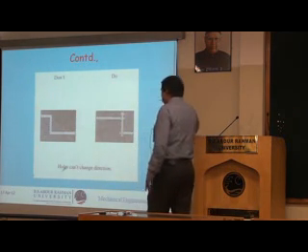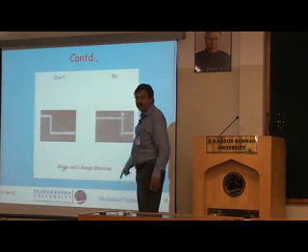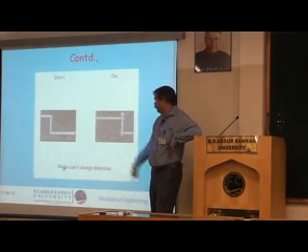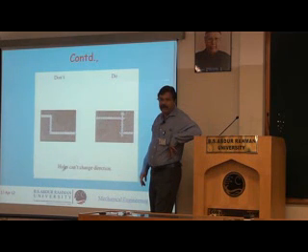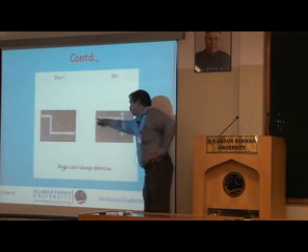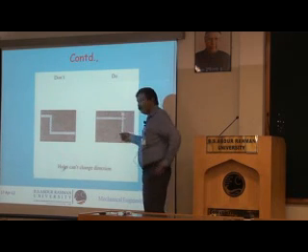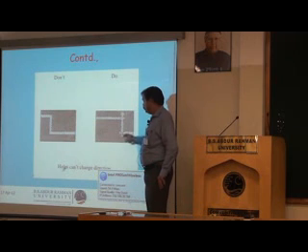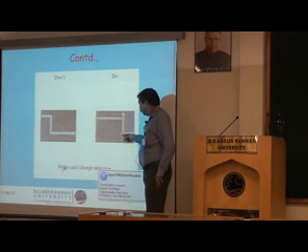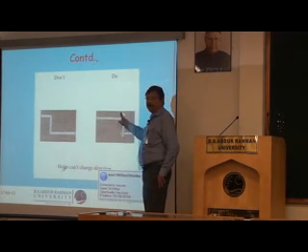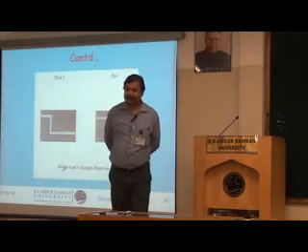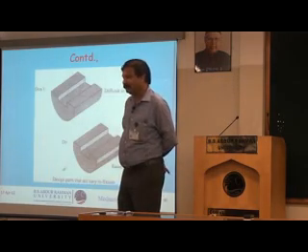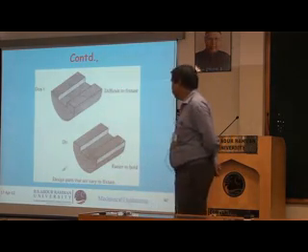So don't provide change in directions for the hole. This cannot be machined. It has to be cast. The thing on the left cannot be machined. It has to be cast. On the other hand, I can drill one hole here, another hole here, third hole here. Probably I may have to plug it at the points that I want, so that I can obtain the same shape. I cannot ask my drill bit to bend after some distance. No, that's not possible. Next.